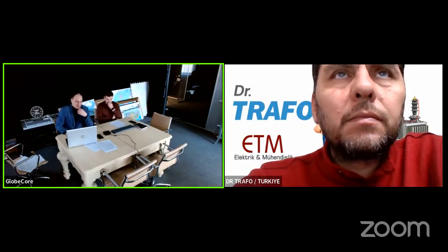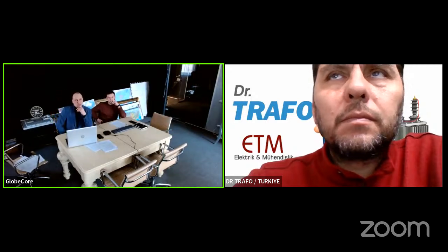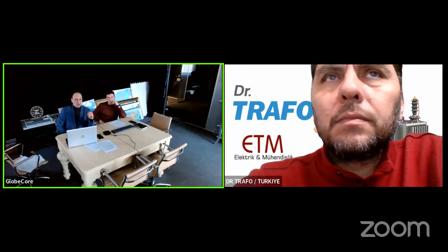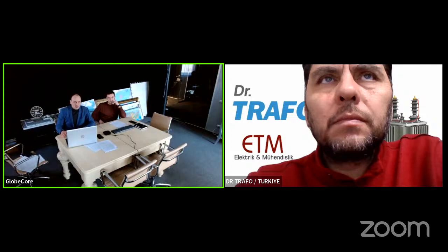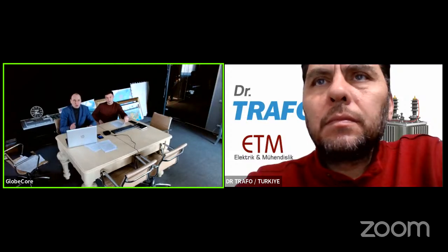What temperature should you also use for vacuum? I understood your question. Look, we can set even plus 90 degrees, but the effectiveness of degassing and the effectiveness of water elimination will not be so much increased, because it is proven by many different investigations that the most accurate temperature is between plus 50 and plus 60 degrees. So within these limits, you will achieve the best results in terms of oil treatment.